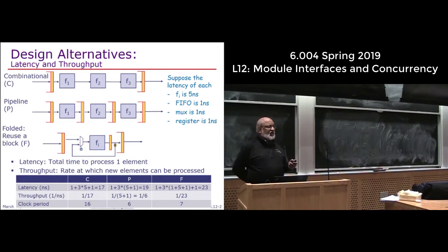The pipeline one will produce a value every 6 cycles. Much higher throughput than the first one. So that's something desirable. If you are trying to process lots of things, we worry about the total time of processing n things. And if you can keep shoving it in every 6 cycles, obviously the total time to process n quantities will be much lower.